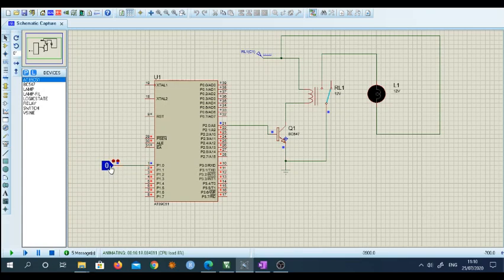When I turn this switch on, that means when this toggle switch becomes 1, I want this transistor to get turned on. When it turns on, this is a DC supply I am applying to the coil of the relay. When this transistor is turned on, the coil gets energized because current starts flowing through the coil, and once the coil is energized, the relay gets switched. Now you observe this relay here. This is a common terminal. This is initially the NC terminal, normally closed, and this is the NO terminal, normally open.